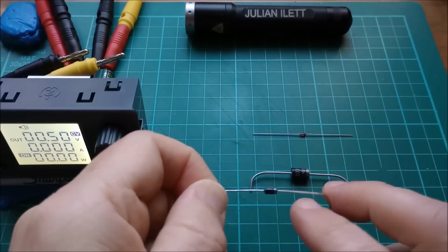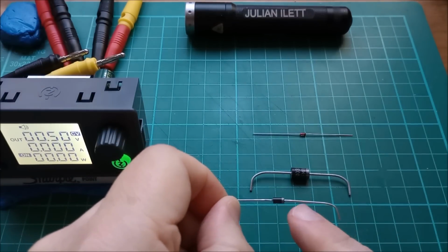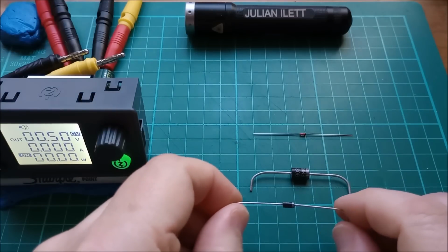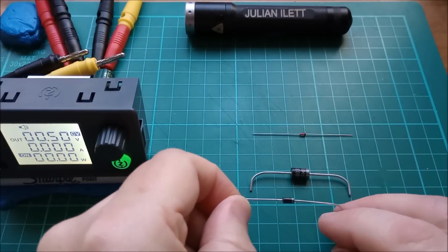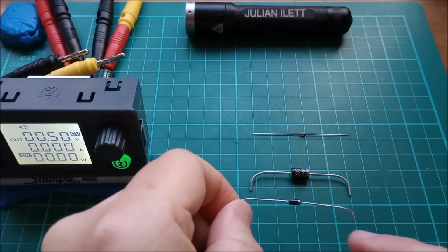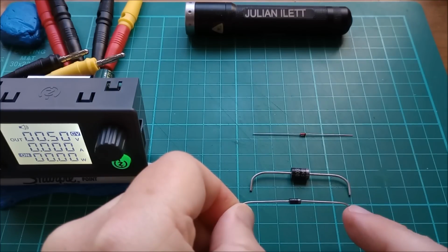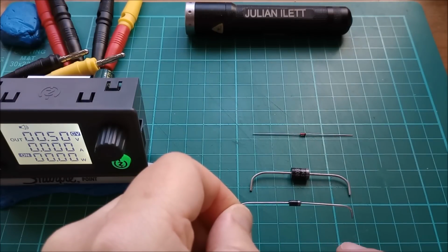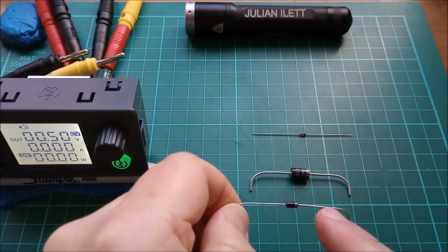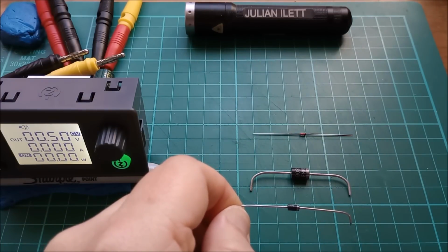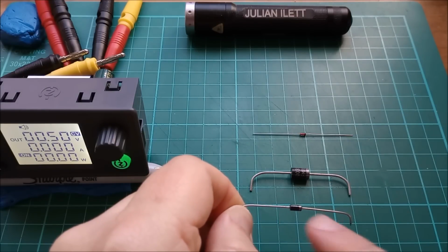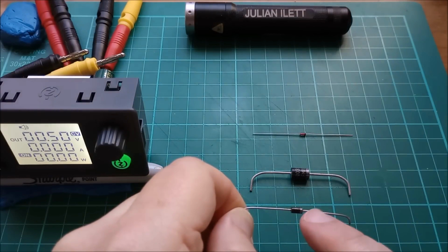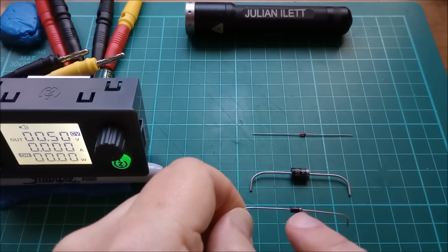So although diodes work as a one-way valve for current, it'll only pass from anode to cathode, not the other way. They're far from perfect. One of the major problems is the forward voltage drop. So once you get to the point where enough current is flowing through the diode, you've got a voltage difference between the cathode and the anode. And the problem is, when you've got current flowing through a diode and a voltage across a diode, then you've got power dissipation within the diode.